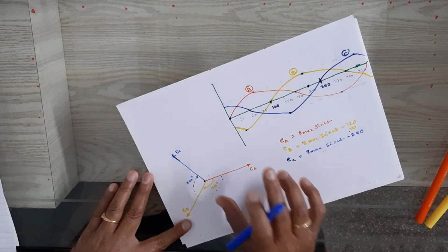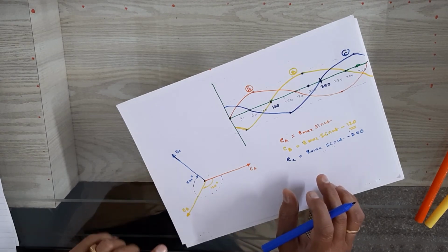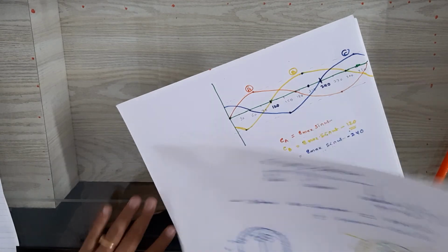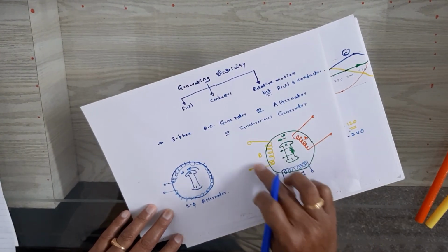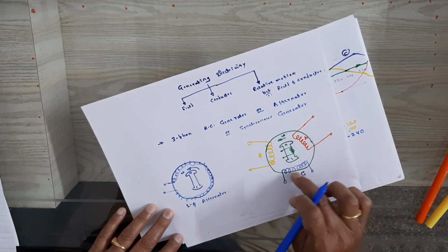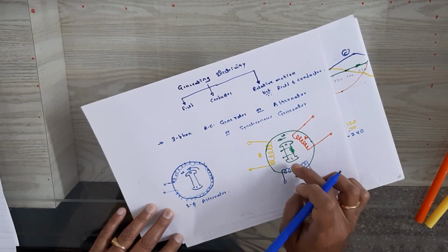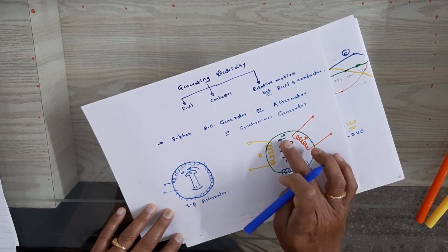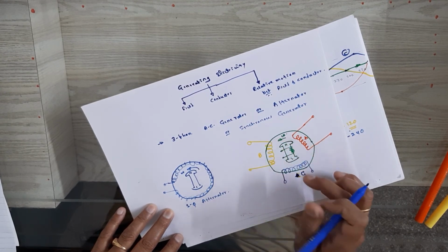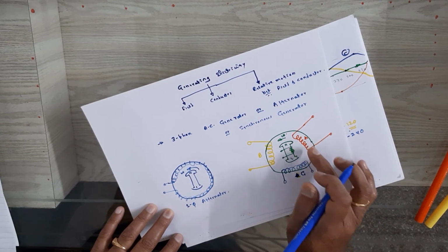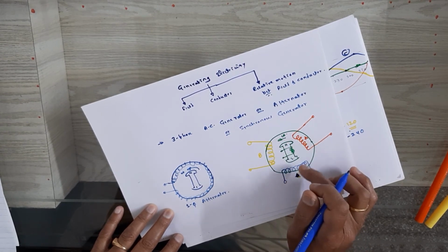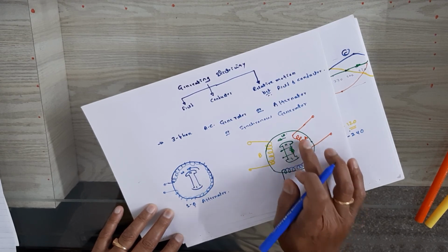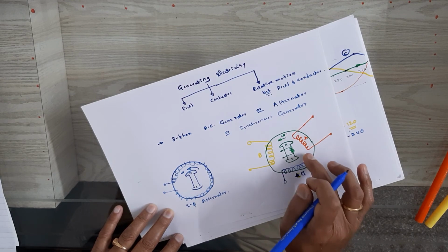That is the summary of the generation. In the three-phase alternator we have three similar coils. These are displaced by 120 degree and a field system is rotating with the angular velocity omega. Because the coils are identical, the induced voltage in all three coils A, B, C is equal in magnitude.